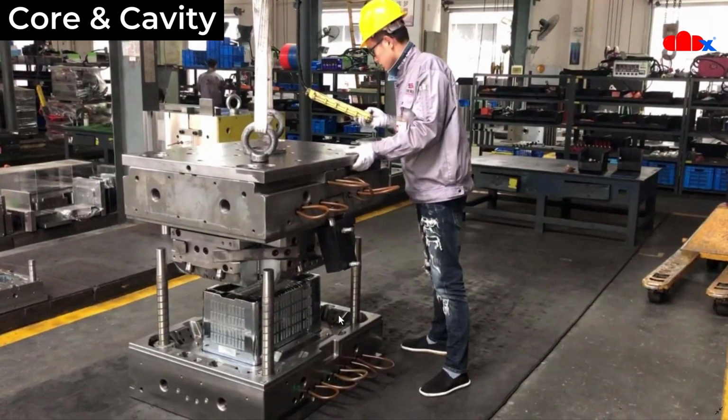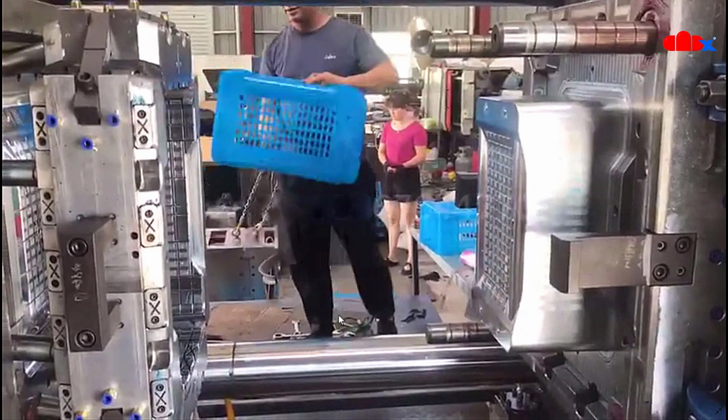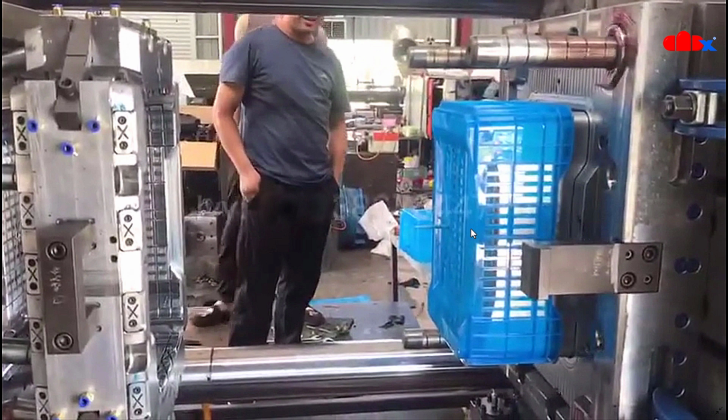So once the mold design is done, the entire assembly will be mounted onto the injection molding machine, which looks like this. So here this is the core assembly and this is the cavity assembly. So both will be assembled together. This core will go inside this, then the molten plastic will be injected and the crate will form. This will be left for some time to cool down, and once the crate is cooled, the core assembly will move out holding the crate. Later on, you can take the crate out by your hand. So this is how the whole process takes place.